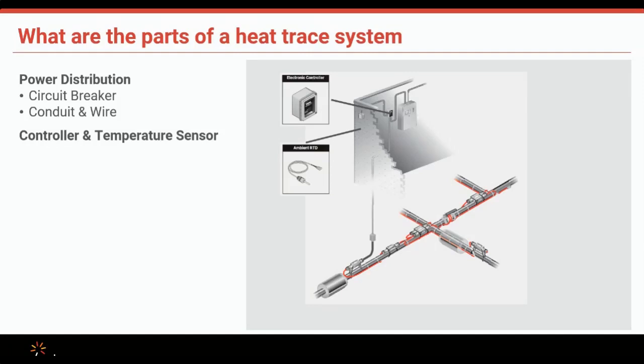However, there are things to consider for your client and the specifications. Without a controller, you have no way of completely turning off that heat trace. So even though it does self-regulate, if someone forgets to turn off that breaker in the springtime, it will continue to produce a minimal amount of heat throughout the summer months. It's really just an energy efficiency thing, and also life expectancy of the cables. So we really encourage some type of control. And again, we have several types, so we can discuss what is best for your client.